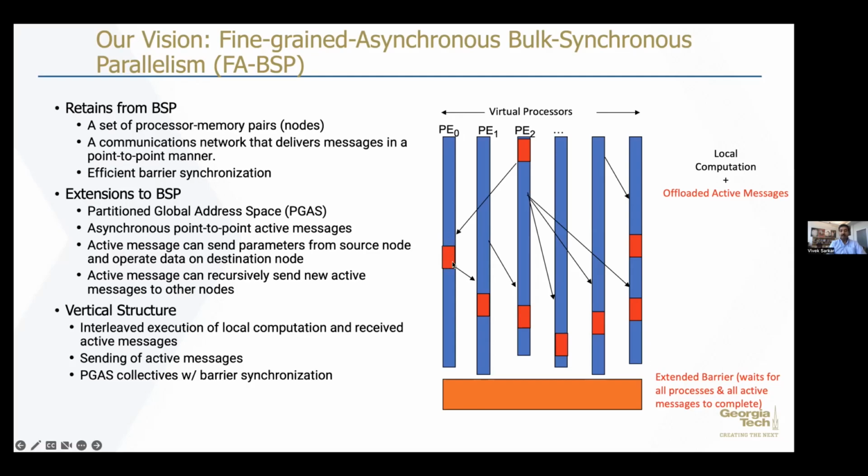And the event handler could result in generating a new message that in this case goes to PE1, but they're asynchronous. So there's no interrupt over here; as in a cooperative scheduler, there are certain points where the runtime will check to see if there are some messages that need to be executed, and otherwise continue with the local main program with the PE code.